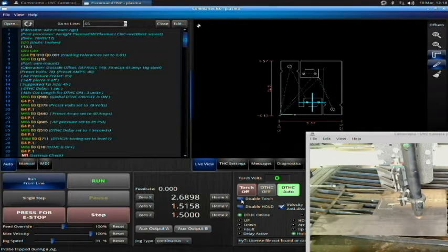Okay. Now this can happen for a lot of different reasons. Everything inside the tip of the torch has to happen in a perfect sequence in order for that arc to fire. If anything is wrong, then you will get a misfire. Misfires can be caused by low air pressure. As your consumables start to wear, you will find that you get misfires. Brand new consumables might go great. Near the end of the plate, you'll start to get some more misfires. Okay, it's totally normal, and it's the most common error you will see. So we're going to talk about that first.